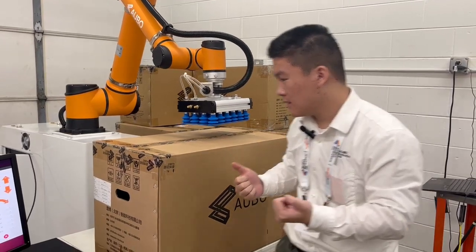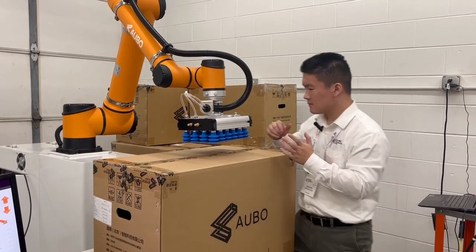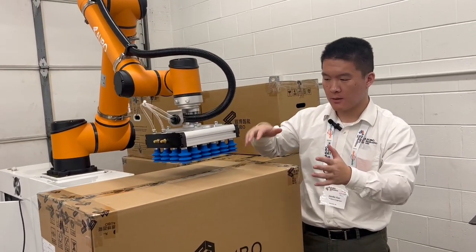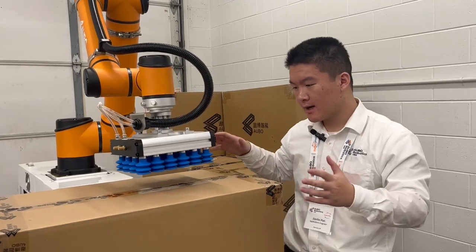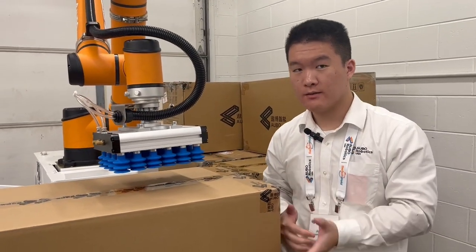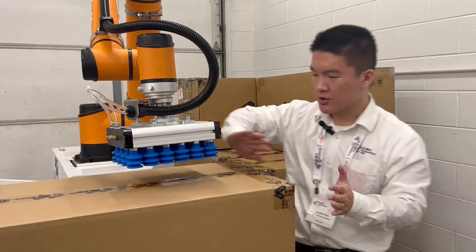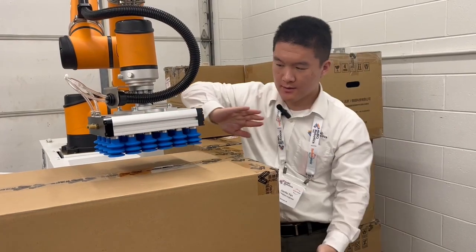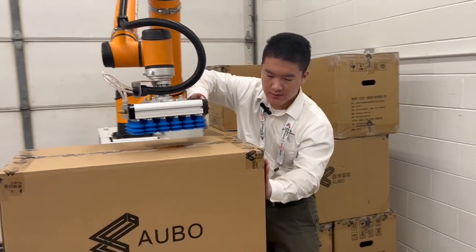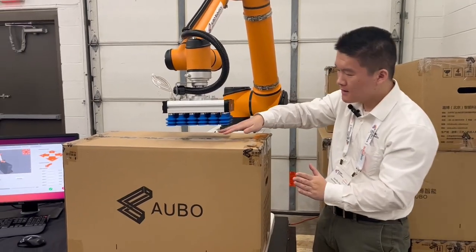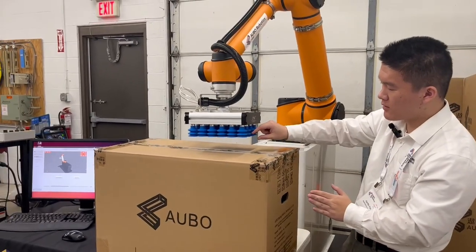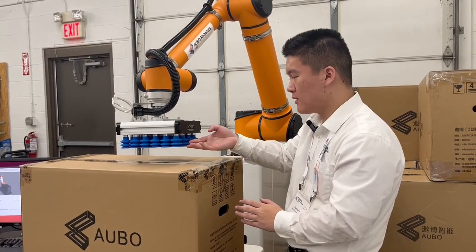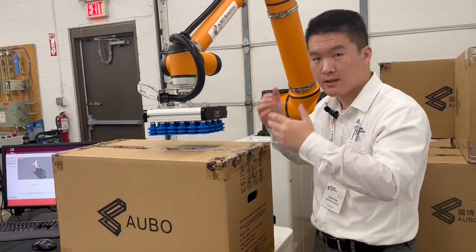So that's important. And also we have to make sure that we are not programming the center pick location for the box. Instead, we are calibrating the origin of the conveyor. So with that being said, we have to make sure this surface is aligned on this surface, and this surface is aligned on this surface. At the same time, the height is low enough to make sure there is a certain compression of the suction cup, so that when there's a vacuum, it can pick up the box.